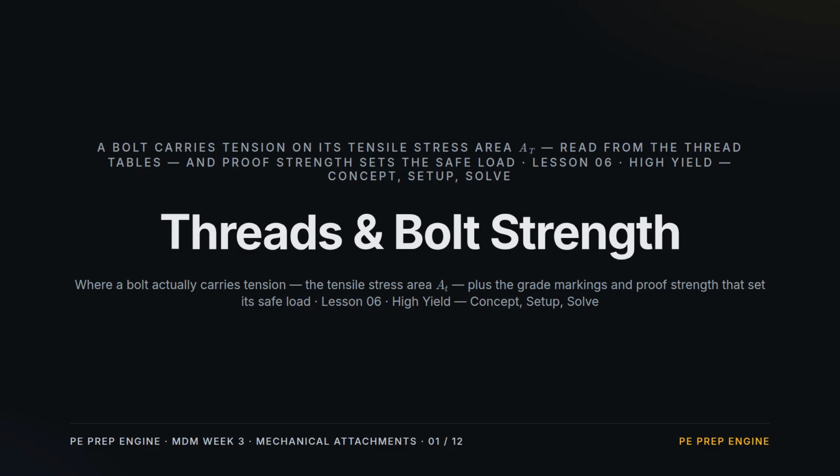Week 3, Lesson 6, Threads and Bolt Strength. Every earlier lesson treated a bolt as a plain shank in shear. But a bolt loaded in tension carries that load through its threads, and the thread reduces the area that actually resists. The tensile stress area, smaller than the nominal shank.